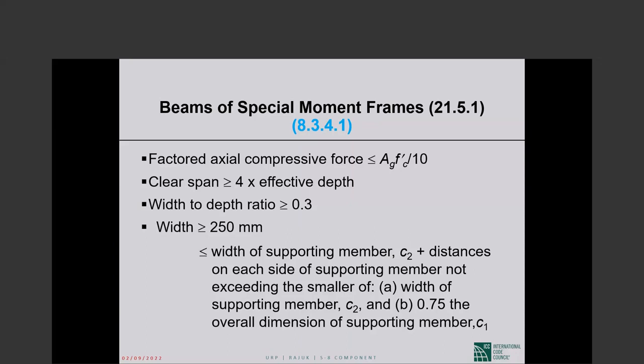In ACI handbooks, flat plate example, there is a minimum unbalanced moment, a function of dead load and live load at subsequent panels. That is added with the 1.2D plus 1.6L for punching shear calculation. We don't see it in your slides. Do we need that? Dr. Ghose, are you aware of anything like that? You have to read the whole thing.